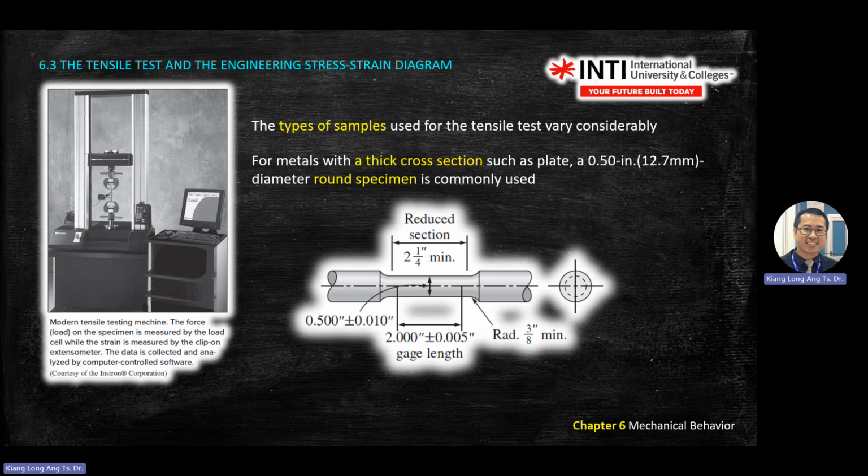When you conduct an experiment and need to do comparison, you need to fix some parameters. For example, you fix the shape of the sample, then by changing the material and testing, you can do comparison. If you change the dimension and then test, it's like comparing apples to oranges already, so you're not able to make a very sound comparison.